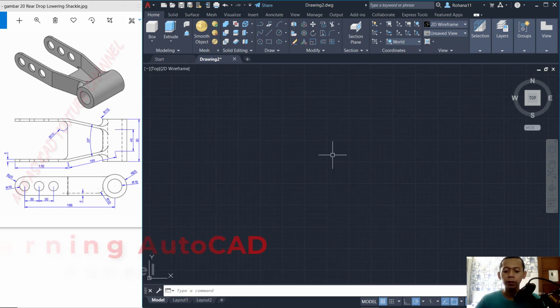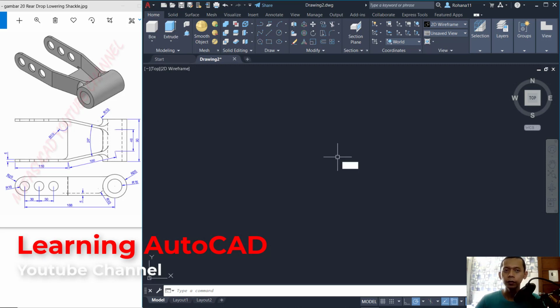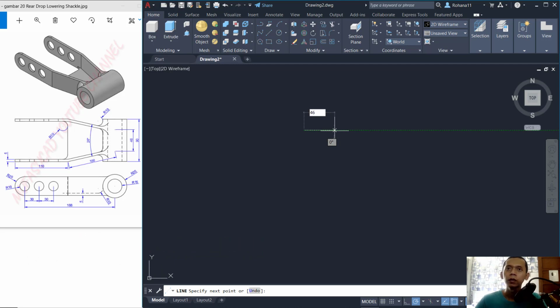First, I will press F7 to hide cut and we can create a line. Start from this point and drag here, I will set 46. The next, you can move to the bottom here, we can set the length to 100. And then you can press the Tab button to use angles. We can set the angle here to 73 degrees and you can press enter. The next we can move to the bottom here with length 110. You can press the escape button to close.